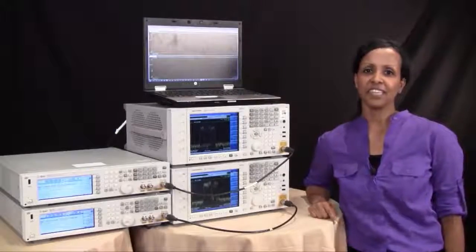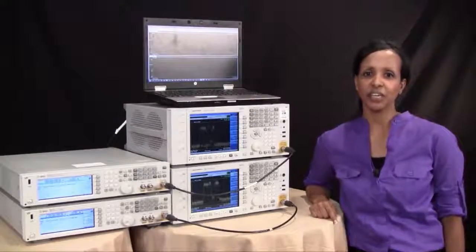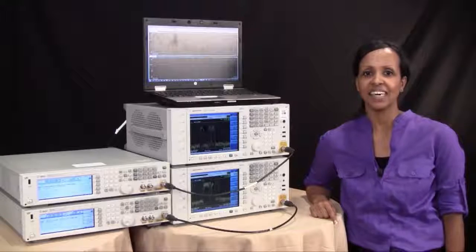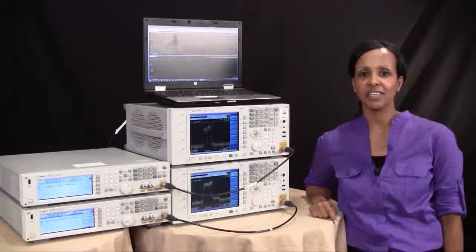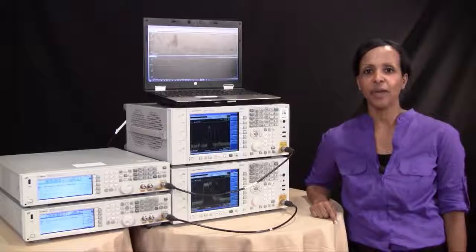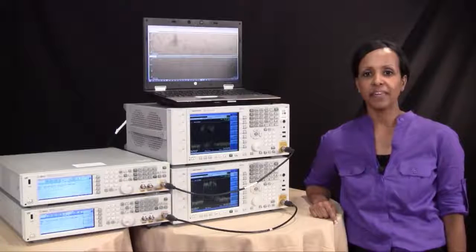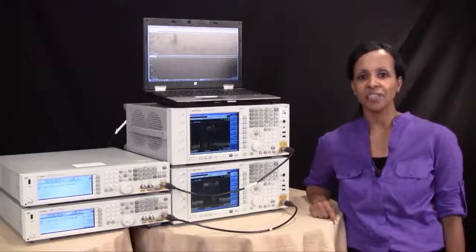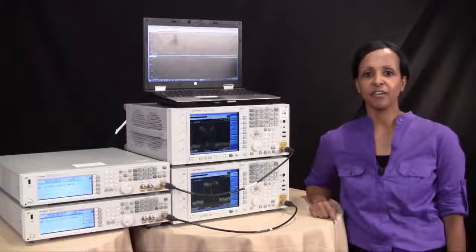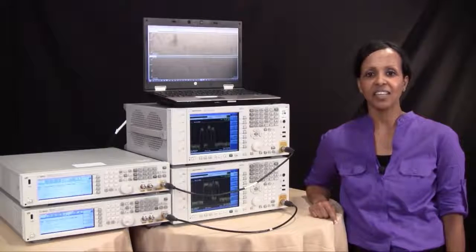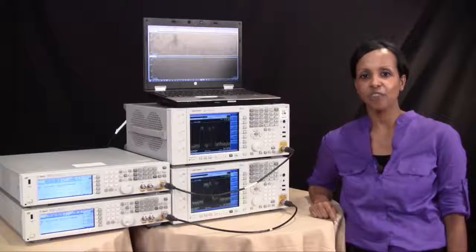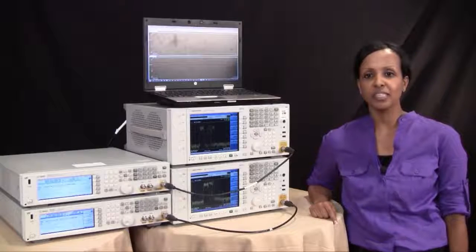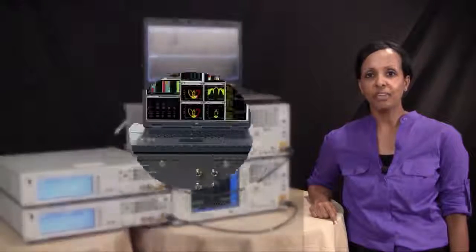One of the major physical layer test challenges is demodulating these component carriers simultaneously, since the frequency band separation in the interband scenario is wider than the IF bandwidth of any commercially available signal analyzer. What you will learn in this video is how Agilent addresses this test challenge with the 89600 VSA software, along with dual X-series signal analyzers or the N7109A multi-channel signal analyzer.